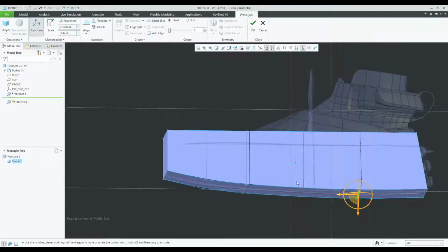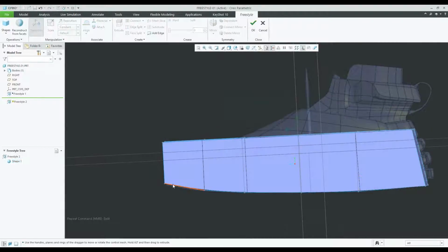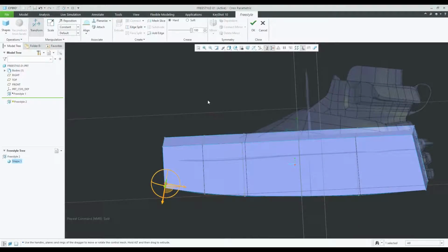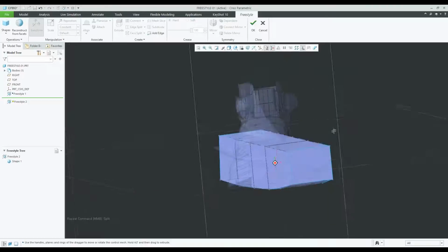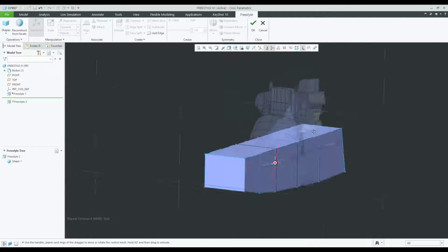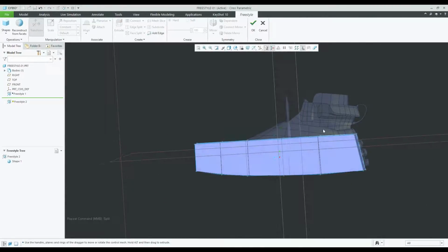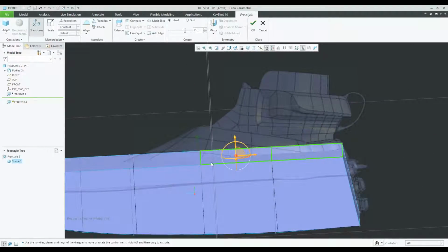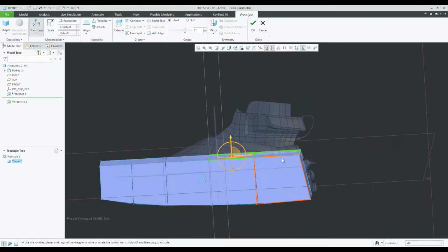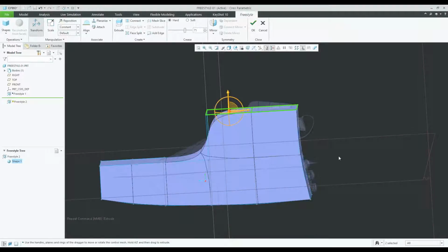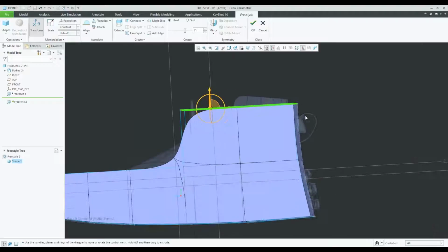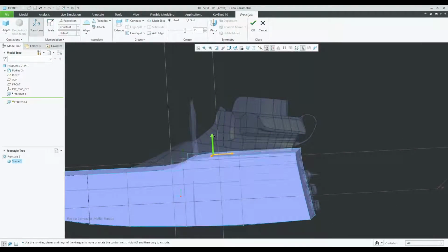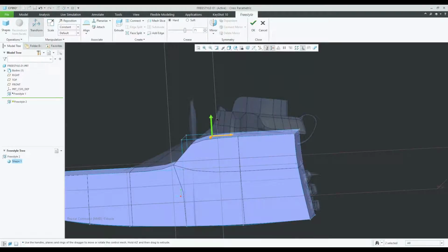And then same thing here. I'll grab this front edge as well and drag that down. You can see that we just started to develop the profile here, the shape, but we have a little bit more to add. So let's grab this top face, hold Control and grab that face. Then from here, we can right-click, say extrude. Again, you can see that very easily and quickly we start to develop the shape of this. So let's move that up to right here.